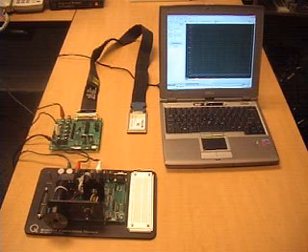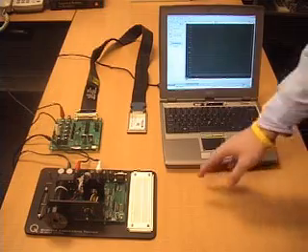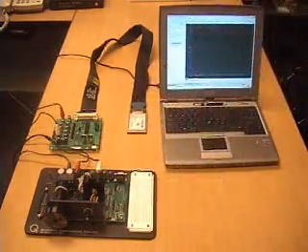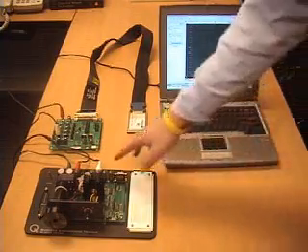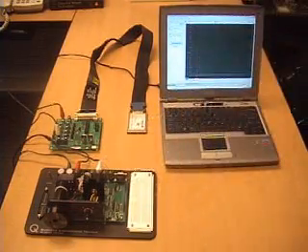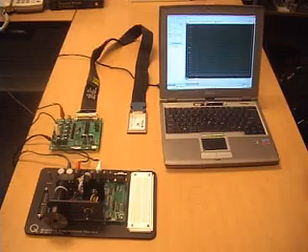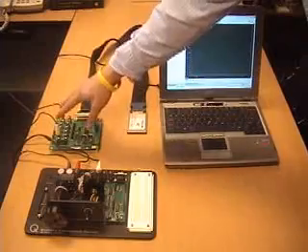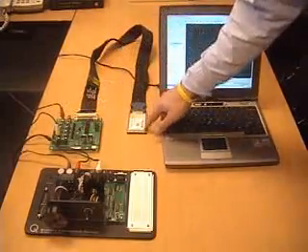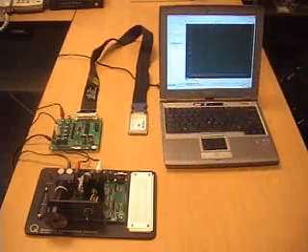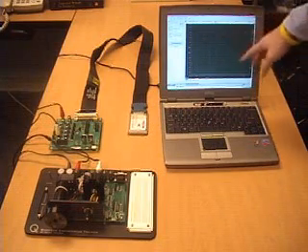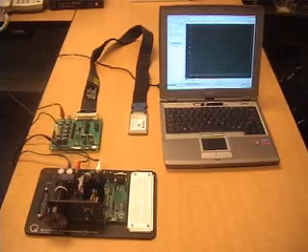Components of the system that we're using here today are the DC motor from Quanser, and essentially I have two signals coming in and out of this DC motor. I've got one which is my command signal, an analog voltage, and then I have a tachometer, also an analog output voltage, and I'm going to interface those to my PC through this interface board, which essentially just breaks out all of the lines available on my National Instruments data acquisition board. So I'll plug that into my laptop and be commanding and driving all of that from my software here on the PC.